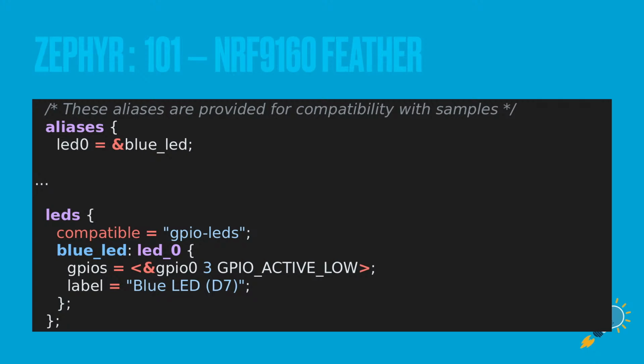So when the output is set to 0 volts, you will get an LED turning on the nRF9160 Feather. I think it's now reverse polarity, and I think this is one of the older definitions. But when you're starting up a new project, you might not have to change or do anything as long as it's set correctly in the board definitions.